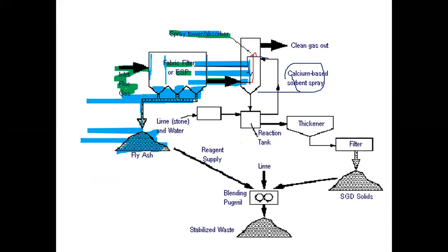There will be a scrubber liquid distribution system to spray it uniformly within the absorber column, and there may be trays or packing inside the absorber column. The flue gas is going up, the scrubber liquid is going down, and they contact each other. Then the water-soluble gases will be dissolved in the calcium-based liquid.